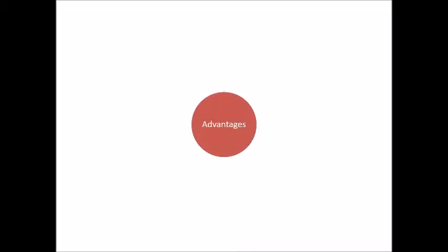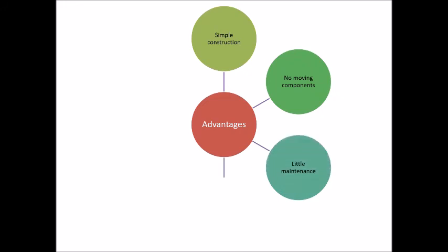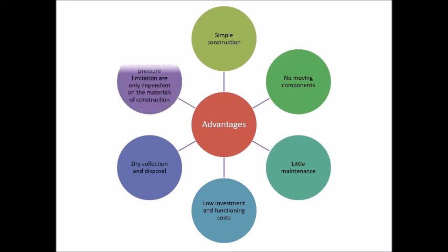There are several advantages and disadvantages in using cyclone separators. First, cyclone separators are beneficial because they are not expensive to install or maintain, and they have no moving parts. This keeps maintenance and operating costs low. As well, the removed particulate matter is collected dry, which makes it easier to dispose of. Finally, the unit takes up very little space.